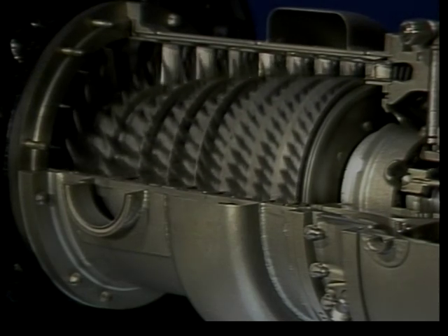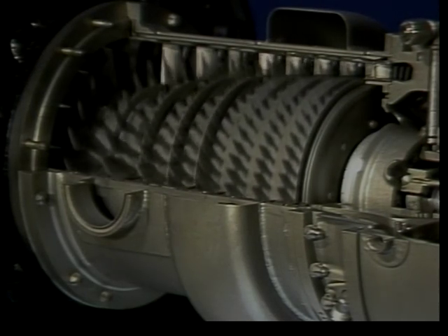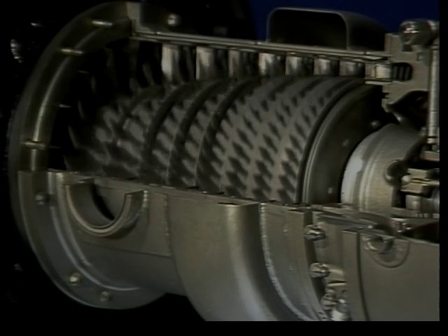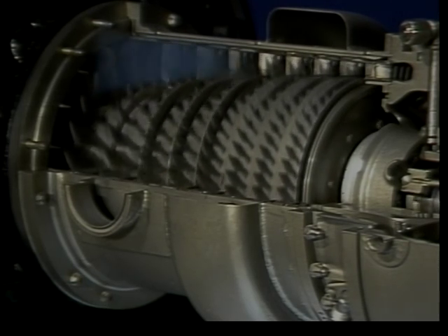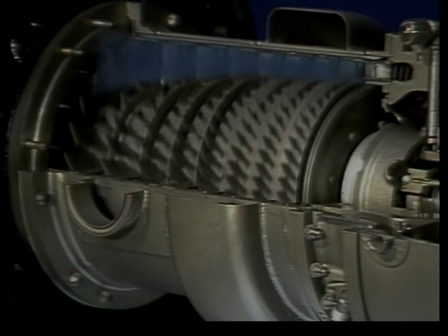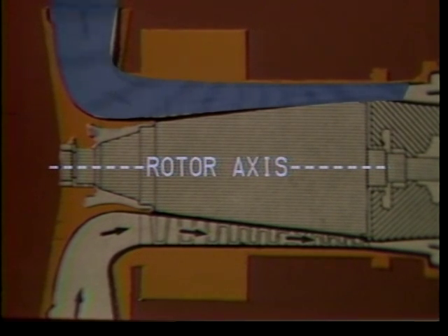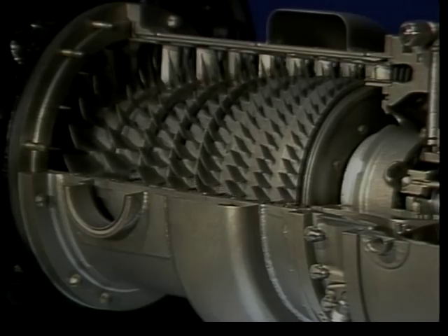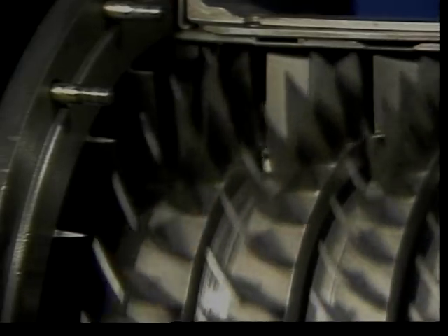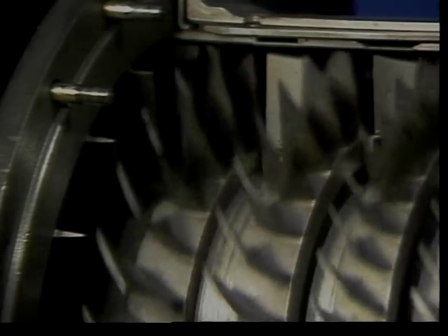The flow path is formed by an annular passage around the rotor assembly. As the air flows along the length of the compressor, the air path decreases in size. Since the path for the air is parallel to the rotor axis, the compressor is an axial flow type. The work of compression is done by several rows of blades similar to the blades of an electric fan.